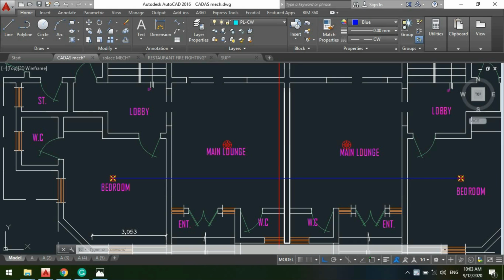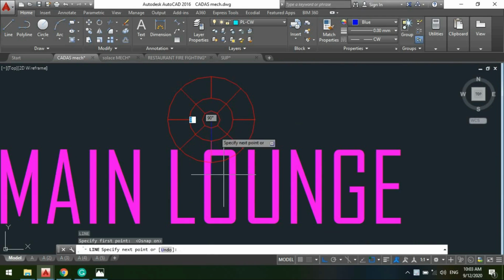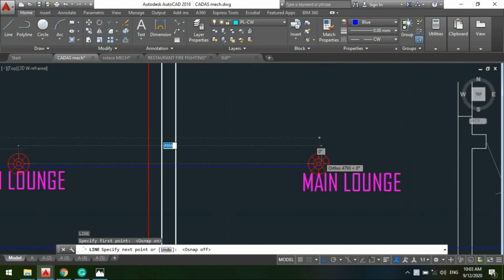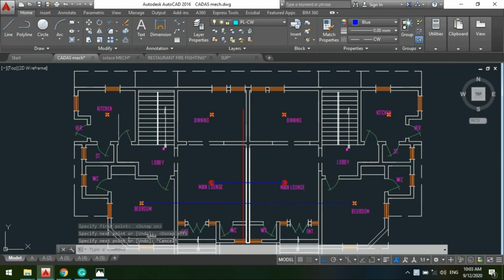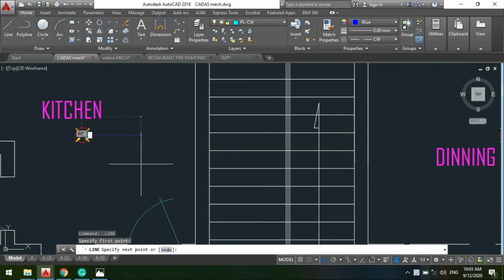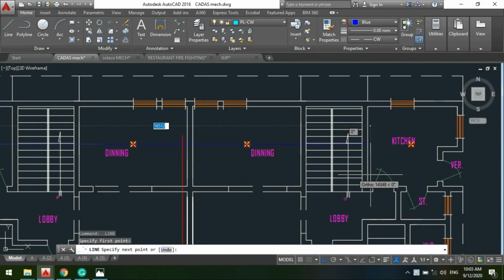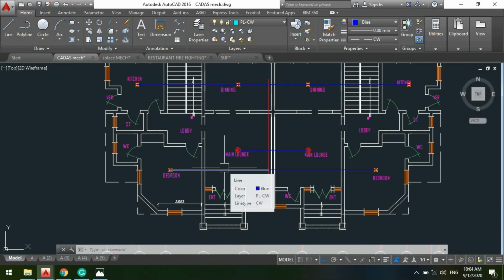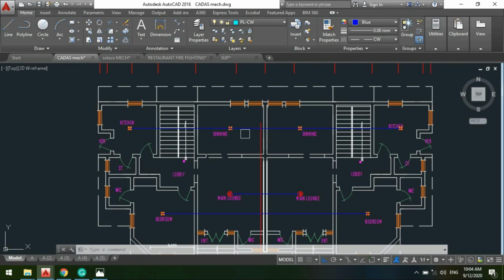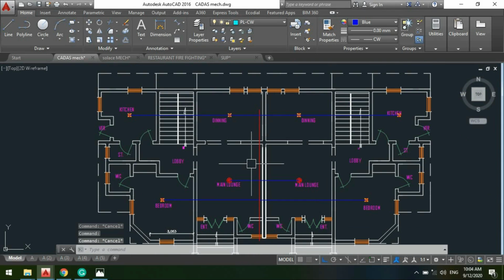So to connect this one, L enter, F3. So I actually create, so considering this, I have a sprinkler head here, another one here. Okay, definitely extend to this. So here is the simplest connection we can have for a tree system, where we have our main here, our cross main here, while the blue lines are for our branch lines.